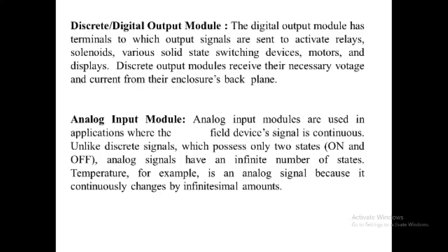We already discussed this in the power circuit of the overall PLC system. The filter protects the signal against bouncing and electrical noise on the input power line, and this filter causes a signal delay, typically 9 to 25 milliseconds.